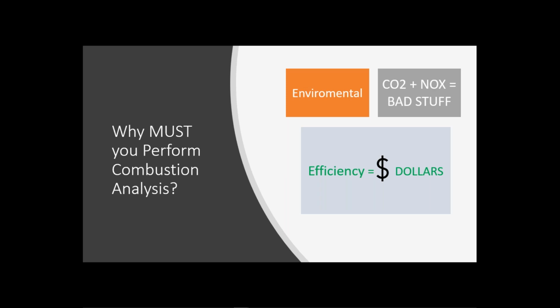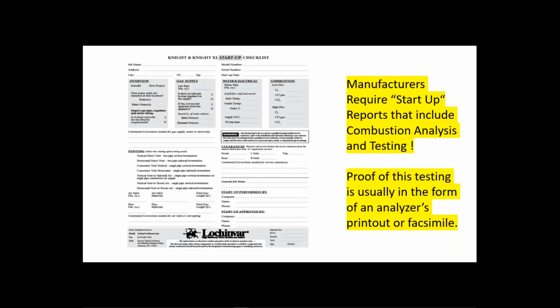Efficiency equals dollars. Absolutely. We want to get the most bang for the buck. We want to get the most BTU for the gallon, the most BTU for the pound, etc. Without this device, you're only guessing. Without a combustion analyzer, you're guessing, and I will guarantee you your guesses are going to be wrong. So the analyzer is of utmost importance.